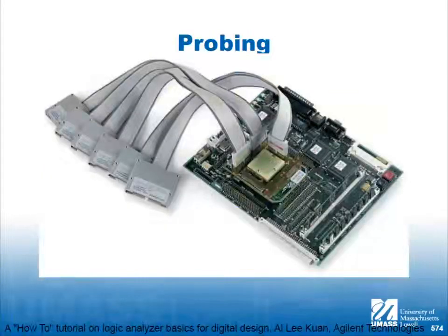So, probing. This looks ugly, doesn't it? There are 1, 2, 3 probes connected to these points. Remember, I said having a lot of clips was a problem, and you don't see a lot of clips here. You see these connectors. They had the forethought on this board to put the part into some sort of socket that they could plug this interposer board onto, and then put the actual part here. Then they broke out the connections of that part into these connectors that were compatible with the logic analyzer.